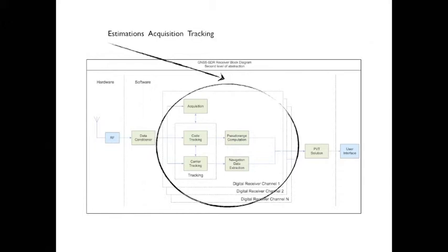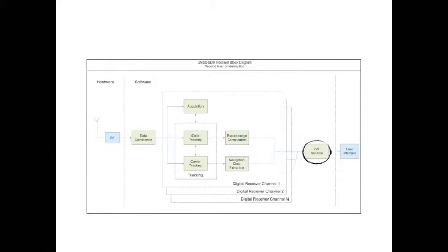In this model, these distances are called pseudo-ranges and are the input for the processing box at the end of the chain. This module, position, velocity, time, calculates the position of the receiver based on these pseudo-ranges and some additional information that is generated during the GNSS signal processing. The model considers that since we need to calculate distances of different satellites, and for this we must process different signals, it is best to dedicate a set of processing modules to each satellite.